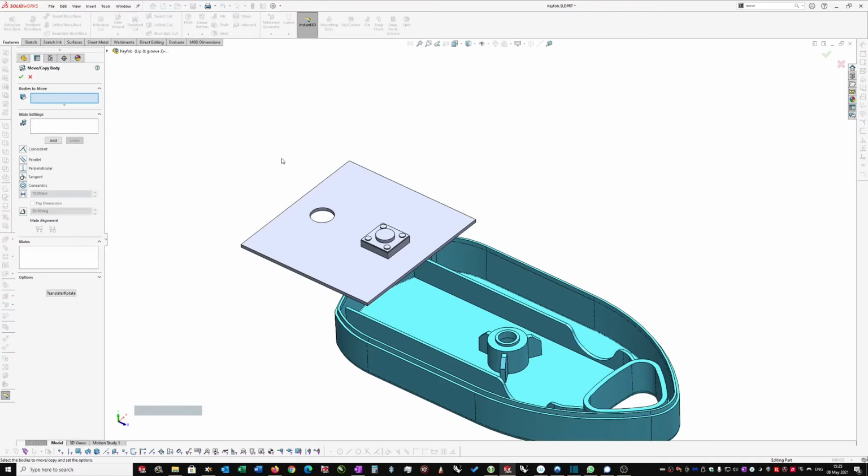If I open that up, the first thing it's going to ask me to do, well, let's just explain these commands in the left-hand side first. So you first need to select the number of bodies, and in this case there are more than one body. So I will select two shortly, and then you can select the faces that you want to connect. And in this, you only have the standard mate command. You don't have any of the special ones available in the assembly feature. But you also have translate and rotate. So you can shift between translate and rotate and constraints. So that button just toggles.